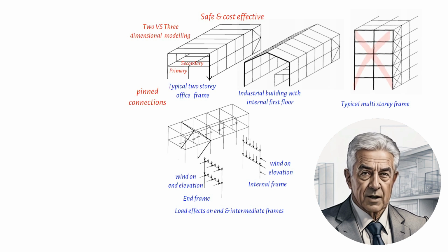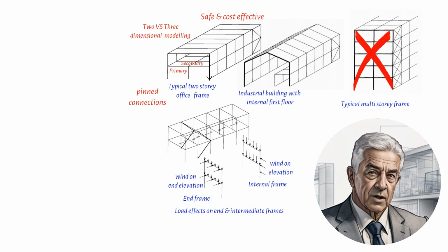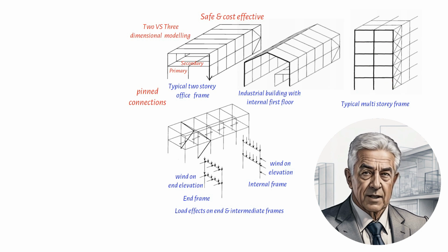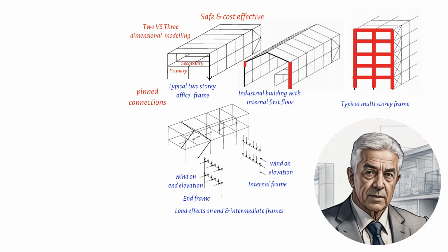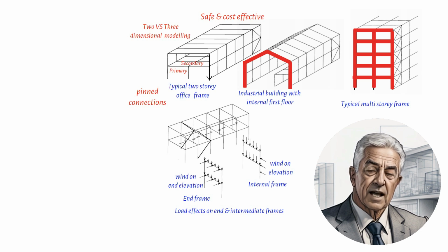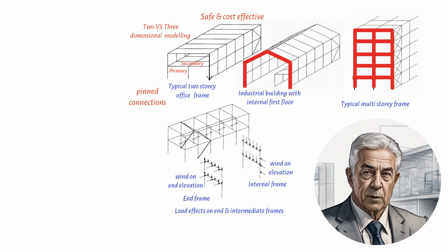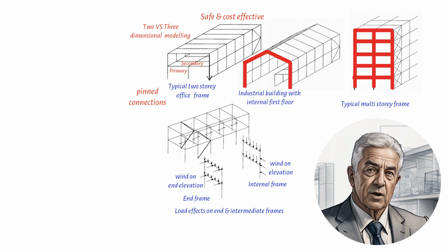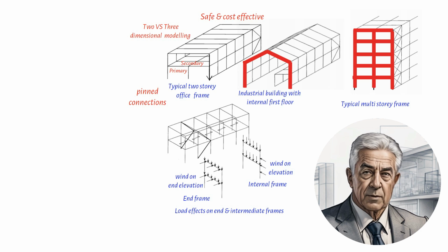Now, in cases where vertical bracing is not allowed in every transverse frame, one solution is to model the transverse frames as rigid, but it may be possible to provide bracing on the longitudinal elevations. This allows the structure to be modeled as a rigid frame in the transverse direction, with ties and bracing in the longitudinal elevation. If bracing cannot be accommodated, discrete rigid frames can be provided in one or more bays to resist the longitudinal forces, and the structure would still be modeled as rigid only in the transverse direction, with a separate model for the rigid frames on the elevations.